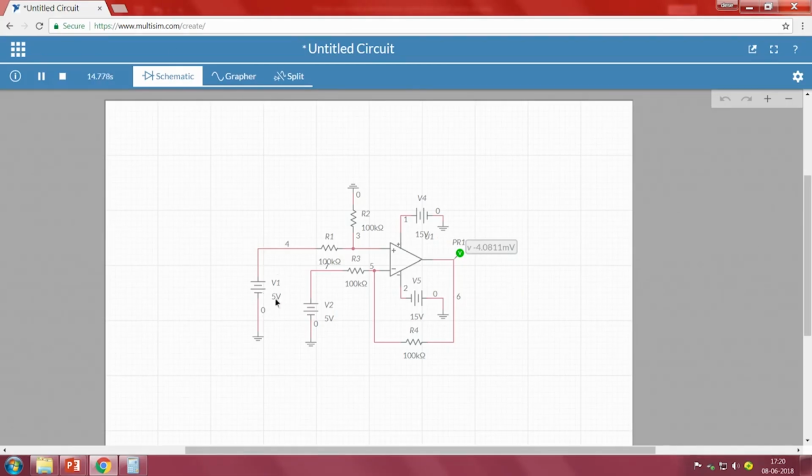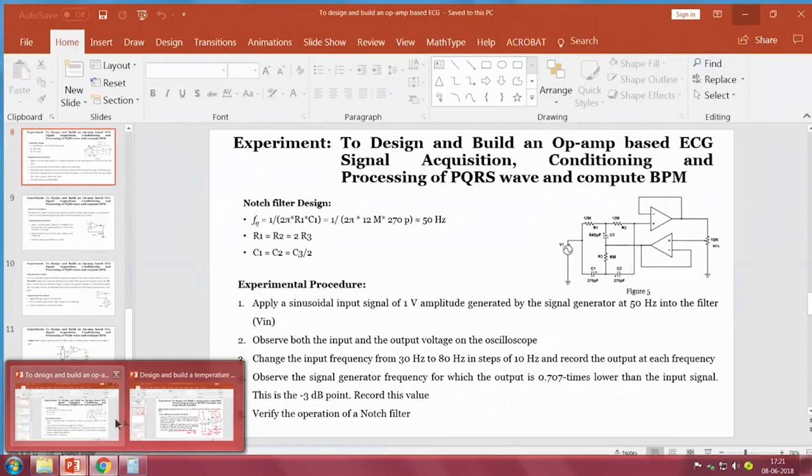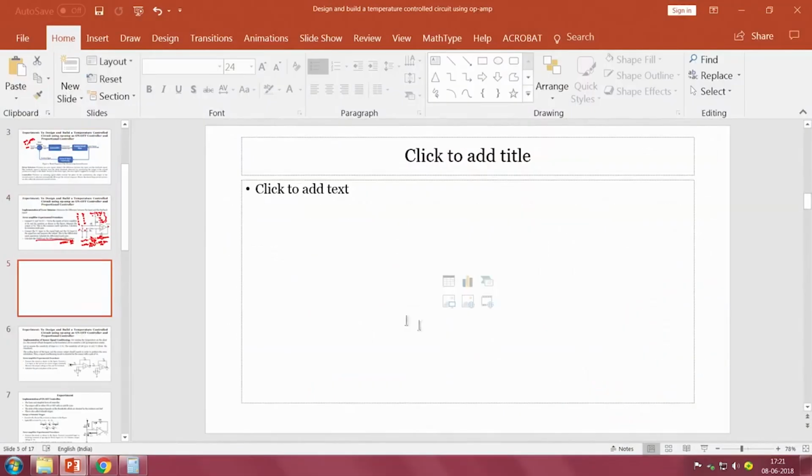So, let me take the value somewhere around 10 volt and this also at 10 volt, should be almost same. Yeah, see when we see 10 and 10, actually the value should be 0, but we got minus 4.1323 millivolt. Now let me put everything in graph and we'll put everything in our slide, and let us see what we get. What will be the CMRR value, right?